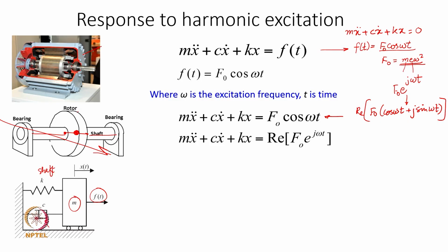Systems are typically considered linear when the amplitudes are small enough so that the restoring force to vibratory displacement relationship is linear. So your constants m, k and c, these elements of the vibratory system, have constant coefficient values. As long as they are constants, the governing equation of motion is linear. So with that assumption of a linear vibratory system.